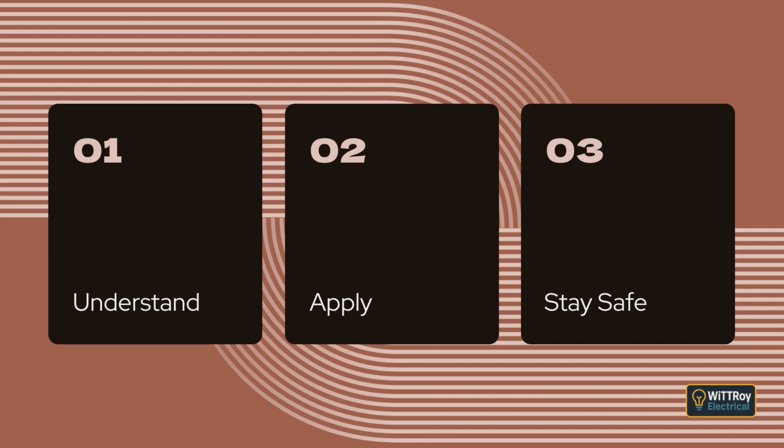Where sheathed cable passes through metallic structural members, an aperture must be bushed or shaped so that the cable is not damaged. If the wiring is likely to be disturbed, the cable must be fixed at a point near the opening. Clause 3.9.3.2 Suspended ceilings.